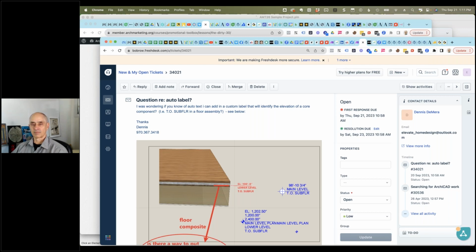But often, in a typical parking slab, you'll have spot elevations that are higher on the edges to make everything drain to the center, but on the underside, it's typically flat in many cases. I have used meshes in the past, but it's pretty finicky. You set your points and give a mesh thickness, then copy it and drop the copy however far it has to go, and then you trim the bottom. Sometimes that works, but if you lose your second copy, it disappears, or it can be confusing.